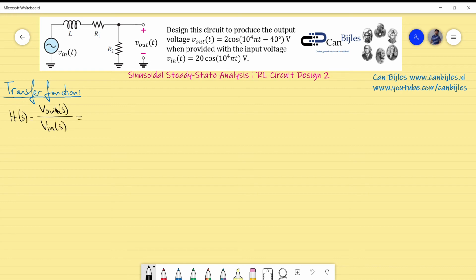And if I want the fraction here, so just the ratio, I would like the V out divided by V in. I don't need the specific values or expression for V out and also the specific expression for V in. That's not really necessary, just the ratio. That means actually I can use the voltage divider rule here. So I can say V out is just actually the resistor or the impedance, it doesn't matter what it is. So in this case, it's just pure resistor. So R2 divided by the impedance seen by the input voltage, which is just actually the complete set in series.